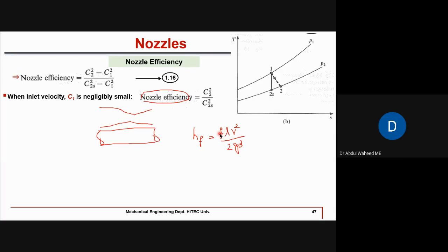Right. So it means nozzle efficiency depends upon nozzle material, its size, its shape, and also this angles of divergence and convergence. अभी इसको हम further detail में study करेंगे. Right. So that's why whenever we want to design this nozzle, all these parameters have to be taken care of for creating a very smooth nozzle, so that the effect of this friction is as minimum as possible. And we want to approach this ideal process, which is the isentropic, means friction-free process.